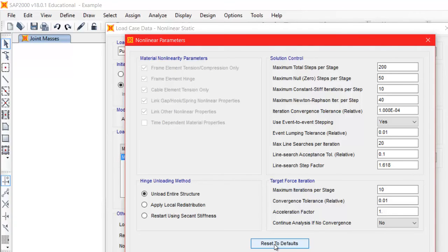to the power negative 4. So maybe if I want to converge easier, maybe I need to relax this value, make it a little bit higher, not very small. And maybe I need to increase the number of iterations. But at one point, it doesn't make sense. So you don't come and say, okay, that's very good. Let's go here and make it like 40,000.